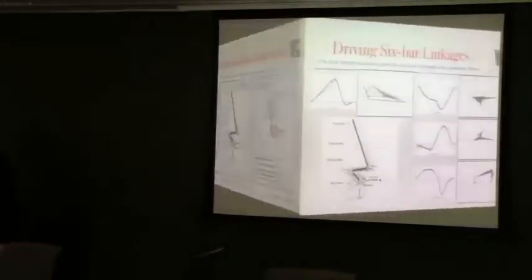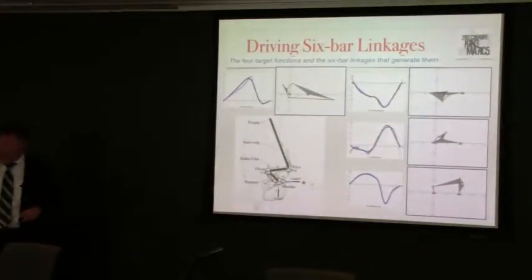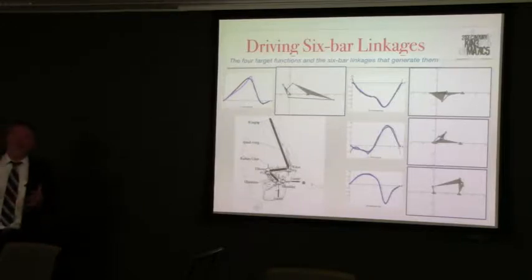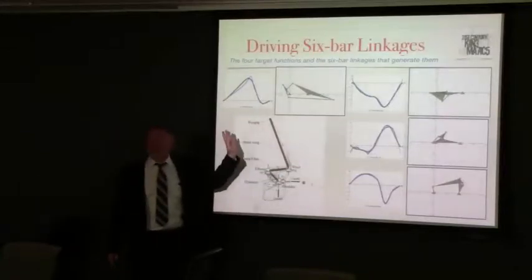Now, just to give you a heads up of what we're doing, from that we did the inverse kinematics for the system and determined what would be the control signals that we would have to apply to obtain the joint trajectories that we wanted. And we tied all of those to a single input.